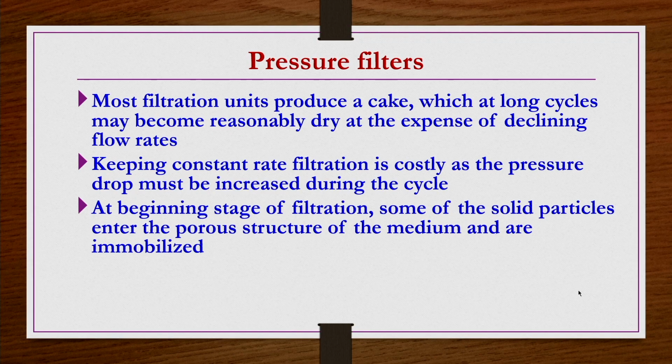At the beginning stage of the filtration, some of the solid particles enter the porous structure of the medium and are immobilized. We have a filter medium with a porous structure. So, at the initial stage of the filtration process, when the slurry comes and interacts with the filter medium surface, some of the particles accumulate in the porous structure of the filter and